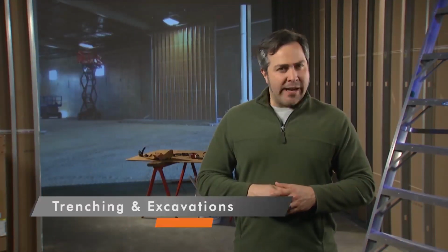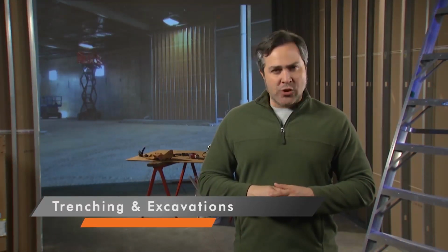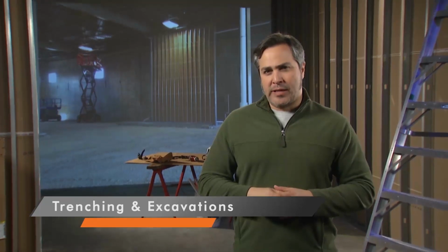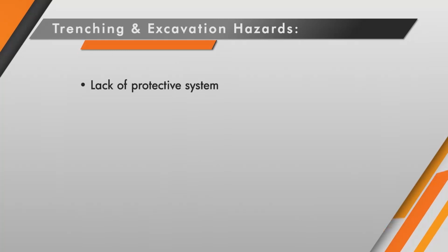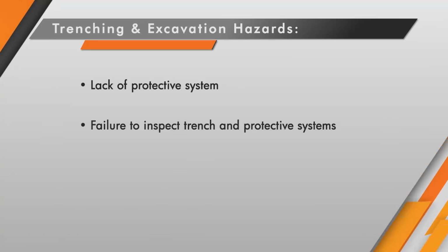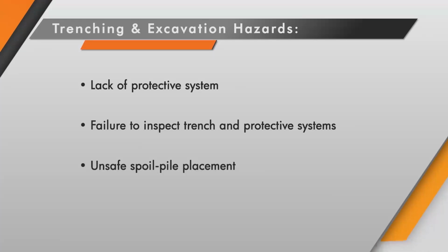Working around and in excavations is one of the most dangerous jobs in the construction industry. There are many hazards you can run into, but most can be placed into 3 categories: underground utilities, confined space hazards, and cave-ins. Most trenching and excavation injuries are caused by lack of a protective system, failure to inspect the trench and its protective systems, unsafe spoil pile placement, and unsafe access to or egress from the excavation.